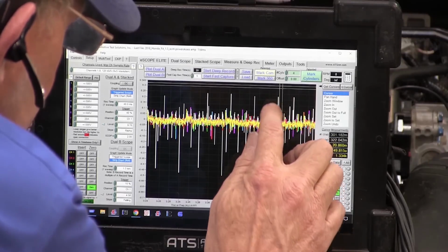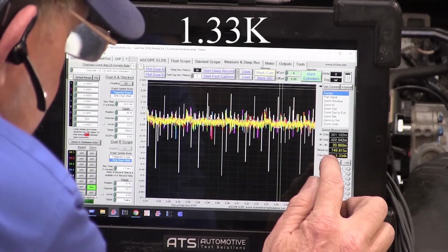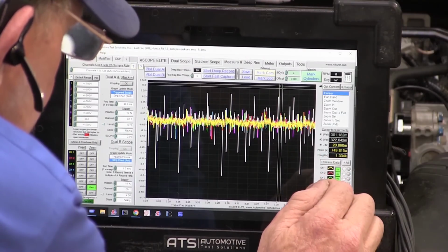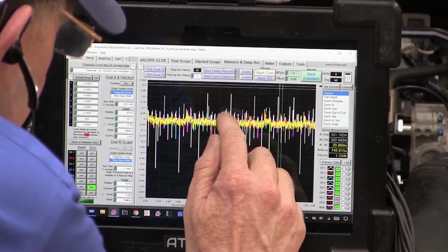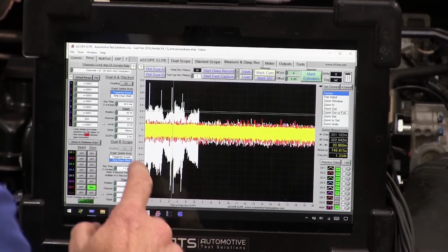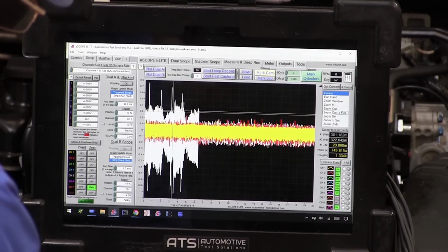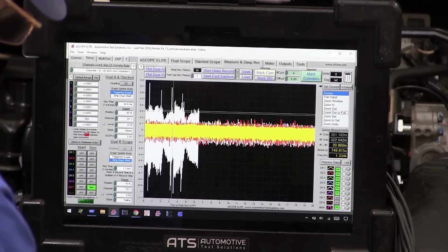Again, going from spike to spike, 133 kilohertz, 749 microseconds. So this is a really fast pulse. But we can see where it got bigger when I opened or activated the throttle. This is the throttle control, and that's a ground on the throttle control. Now, I don't think that's more than I want to see. So I'm going to run a ground from that to the battery ground, and we're going to see what it does. But I don't think that's my problem either. I don't think that's what I'm looking for on this car.